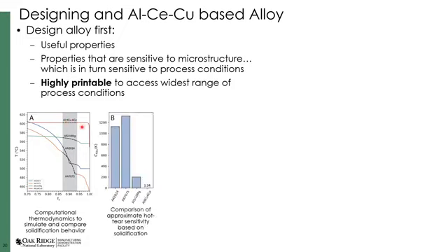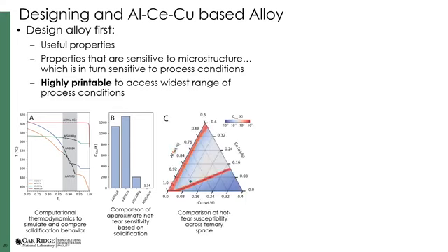And we are able to do some simple approximations for our hot cracking sensitivity. In this case, I'm showing a calculation based on some work by Sindo Kou, and that shows that the sensitivity of this particular alloy composition is quite low compared to some of the conventional wrought alloy compositions or even against aluminum silicon. We can also plot out what that hot cracking sensitivity is across the composition range for the ternary system and select a particular alloy chemistry that we think gives us a balance of processability and mechanical properties.